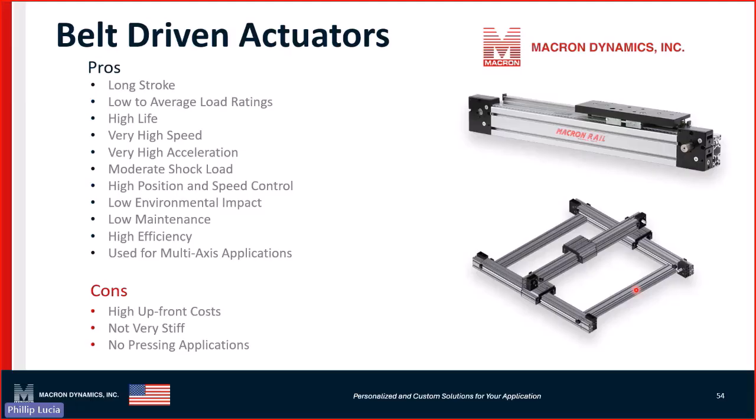They do low to average load ratings. They have very high life because they're using a timing belt. If you can imagine the timing belt or the serpentine belt in your car, those things are good for 100,000 miles before they have to be changed. It's the same technology that's used in these belts. Very high speed, up to 7 meters a second, high acceleration, moderate shock load because it is a belt. It does have some lack of stiffness. You can do very high position and speed control, very low environmental impact, low maintenance because there's really nothing to maintain except making sure the bearings are lubricated properly.